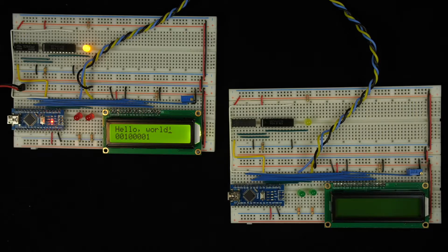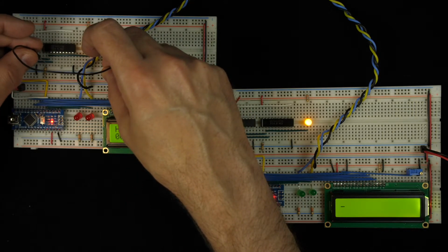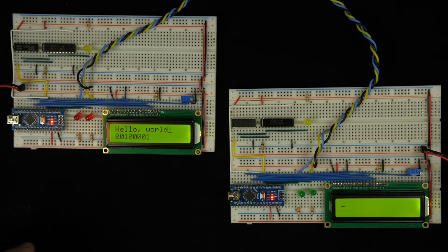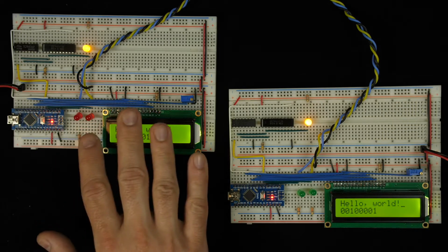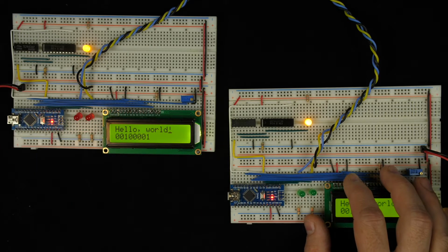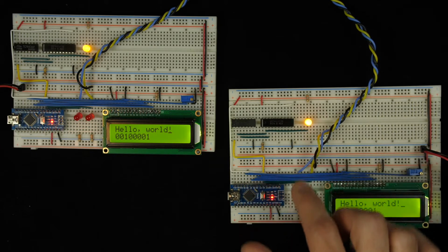All right, so now let's power up our receiver. And so this is where I want to be able to reset the parity bit. So I'll manually connect ground to pin 1 and that should reset it. So now if I reset the transmitter so it resends the message, we should see the parity getting computed on both ends. And if there are no errors, then it ought to compute the same parity. And indeed, it looks like it came to the same answer. So after sending the message over here, we've sent an odd number of 1s. And after receiving the message over here, we've received an odd number of 1s.